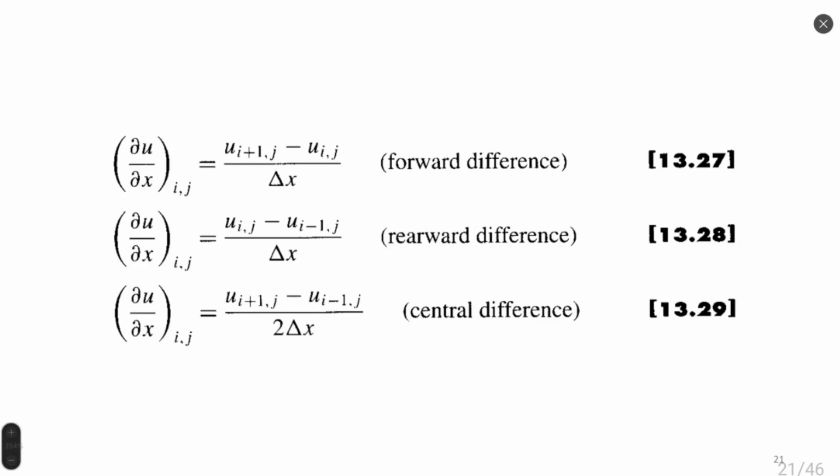Once we choose a solution, for example in Fluent, the implicit model is listed as a set of equations not connected in one system. And in the case of an explicit solution, the explicit method, it's a set of equations which are related inside one system. What to choose is every time a choice of complexity and speed of calculation.